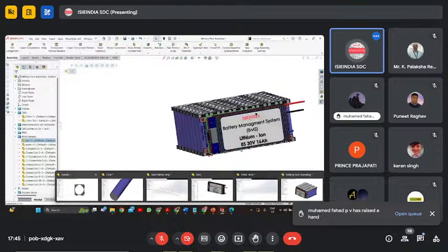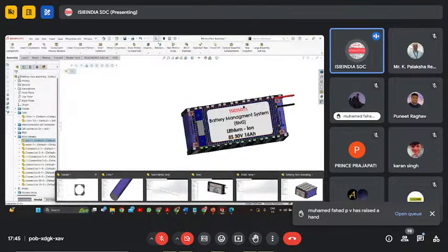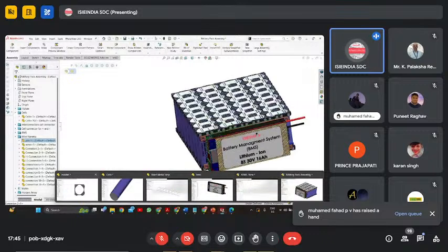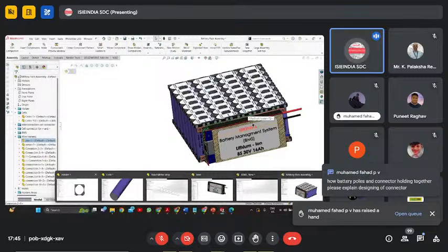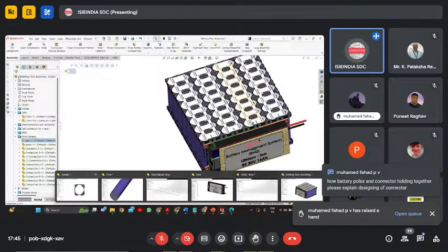So, as you have seen, here I have written 8S 30 volt 16 ampere. 8S means 8 string, meaning 8 cells are kept in series, and these 8 series cells are connected in parallel. Each of these 8 cells connected in series is a cell module, or a layer of the cell module. And when we connect each layer of cell module in parallel directions, it increases the